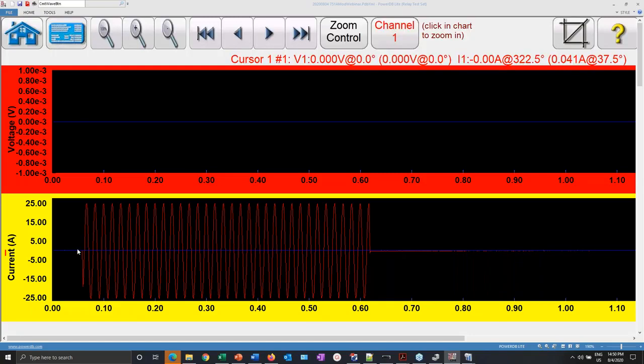Now I'm going to show you what the event looks like, and this is what I'm going to play back into the relay. This is a tool that's used, I would say, in forensic analysis. When I say forensic analysis, I'm maybe taking a name from the movies or from another domain in science or technology, but a lot of times you have a failure or a fault in the system, and you have to play back the events that resulted from that failure to figure out if the relays that were involved in the fault acted correctly.